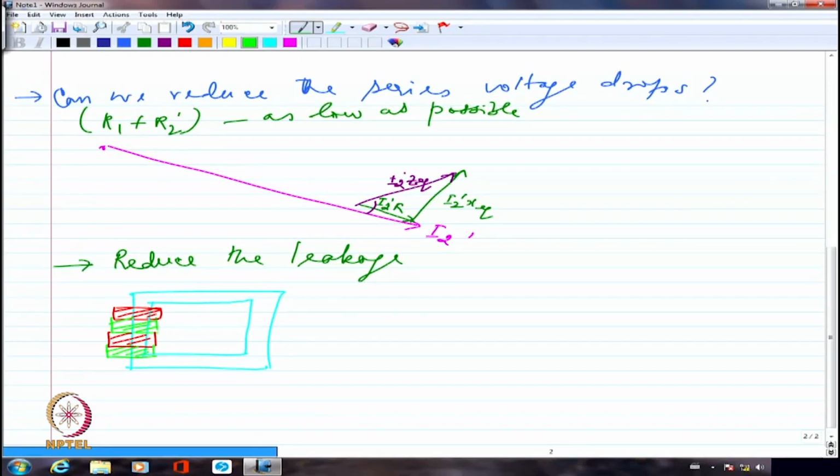So I am going to have the primary and secondary sandwiched continuously, and of course I have to connect these two in series. Similarly, I have to connect these two in series. I have to necessarily connect them, no doubt, because all the turns have to come in series. Only then I am going to get n times the voltage per turn equal to the overall voltage. But I will have essentially primary and secondary sandwiched in one particular limb itself, and the next limb also, yes.